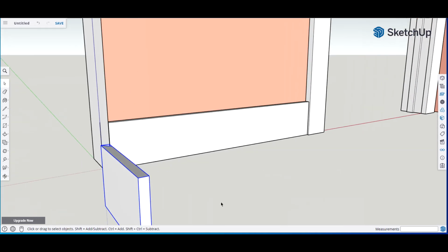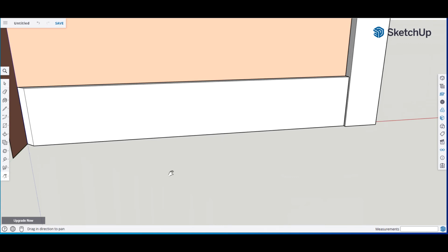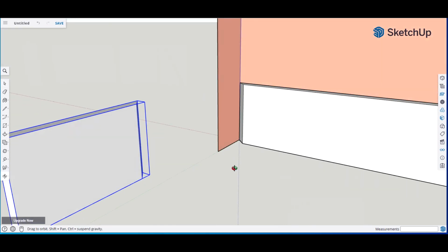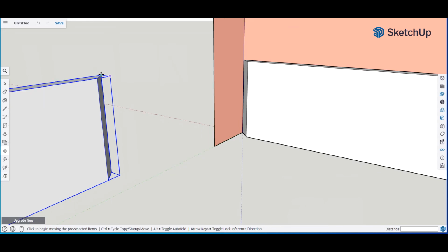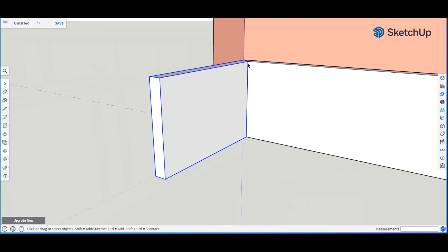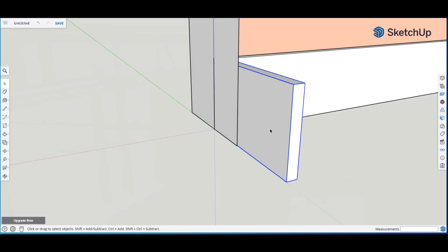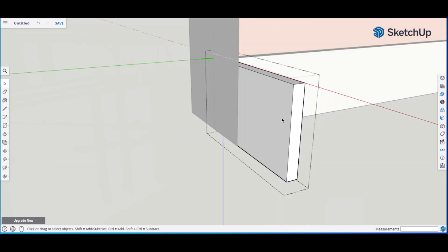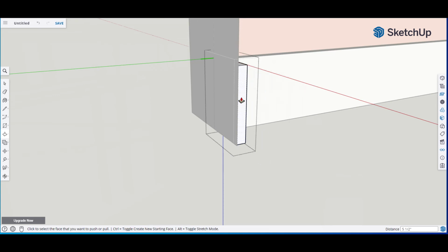And we're almost there. So let's just scroll and zoom in, rotate, and now M. I'm going to grab this corner. Snap it there. Oops. Keep it highlighted. And as you can see, we're a little long here. So let's go ahead and right mouse click, edit component, P, push pull, bring it in, and it should snap right about there.